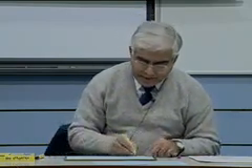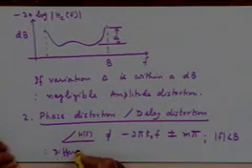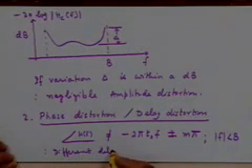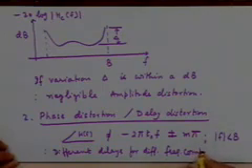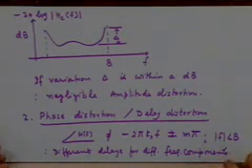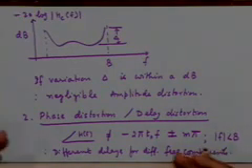So if this linear characteristics do not hold, it implies different delays for different frequency components, and that is why we also call it delay distortion, right? If every frequency component present in the message signal undergoes the same amount of delay, there is no delay distortion, no phase distortion. If different frequency components undergo different amounts of delay, there is a delay distortion.